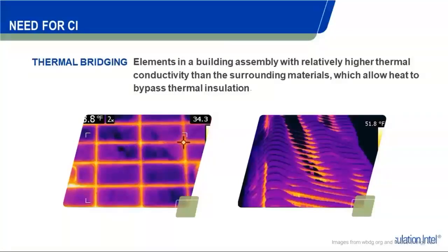With these infrared images, you'll notice that there are some darker colors and some bright colors. The infrared images indicate that the brighter light yellow or orange colors are the conductive materials that are showing up, and that is actually transmitting energy from a building to the exterior. In both of these images, it is pretty apparent.